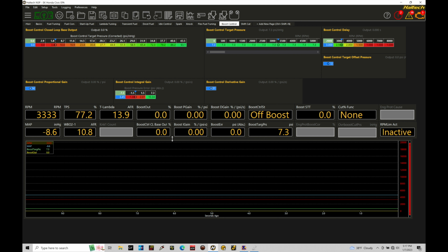Now, some general guidelines I want to talk about real quick. With your wastegate actuator or external wastegate, it's going to be that actuator rated pressure or your spring pressure in your gate. You can typically, on an internal wastegate, double your actuator pressure. So if you have no boost control hooked up and you have just your pressure source going to your actuator, if you build 10 pounds of boost, let's say you have a 10-pound actuator, you can typically double that boost pressure with a boost control solenoid and hit 20 pounds of boost. If you want to hit more boost than that, you're going to need a higher base actuator spring. You might need to put in a 15 or a 20-pound base actuator spring and change that factory or turbo actuator out to something higher to be able to achieve a higher range of boost control.